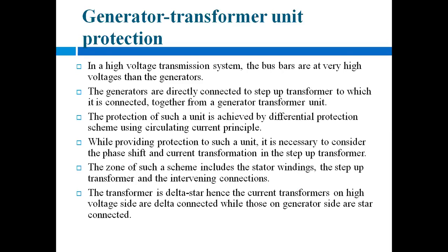There are CTs on both sides and relays on the lower side, with differential protection. Here we are showing only the stator windings, for the generators or alternators.